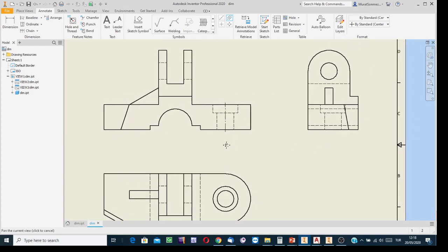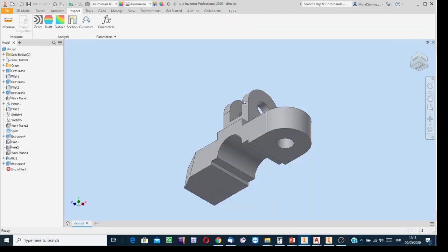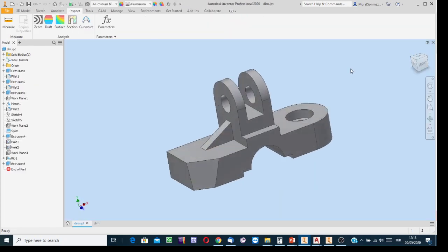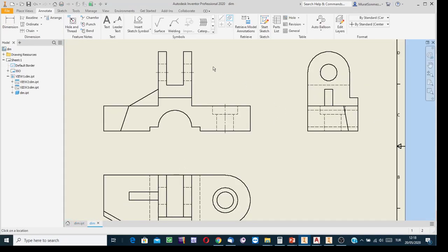What else? Here and there we have the limits of one of the holes within the semi-cylindrical extension. This hidden rectangle is the image of this hole. So to say that it is not the image of a rectangular prism but a hole, show the longitudinal axis.